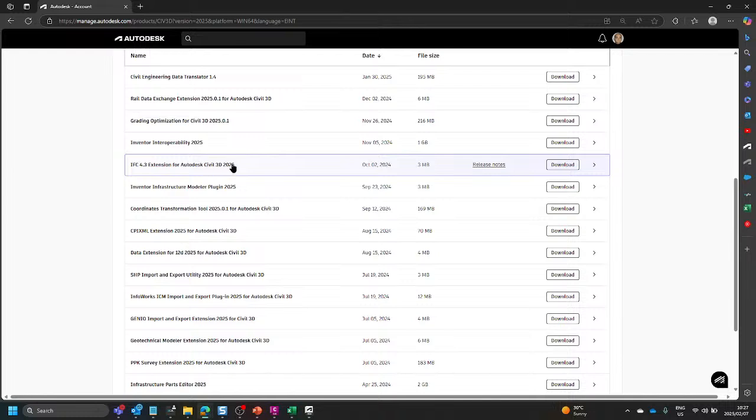That's if you want to export your file to an IFC format, Industry Foundation Classes, which is a generic interoperability file for BIM models. Within the Civil 3D world, we're more familiar with LandXML or just XML, but in this case, the IFC is the default standard for the BIM world.